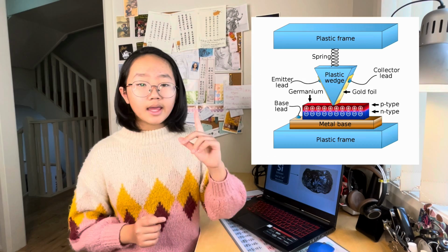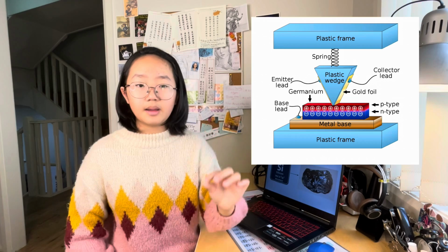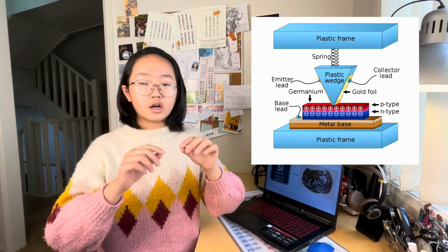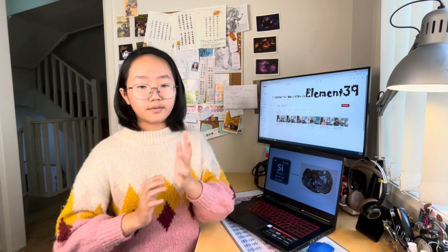The point contact transistor, the first transistor that was invented and the one developed by Bardeen and Brattain, works differently. At 1.5 inches in height, the first transistor was huge. It worked because the gold leaf, separated a hair's width apart, would skim over the surface of the germanium, leaving the surface ever so slightly negatively charged. A small positive current would then be applied to one of the wafers and that would amplify the current. The change in positive current applied to the first wafer would mean a larger change to the second, giving it amplifying powers. However, this type of transistor was harder to produce and was later superseded by Shockley's patent for the bipolar transistor.